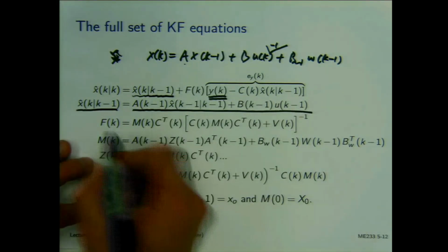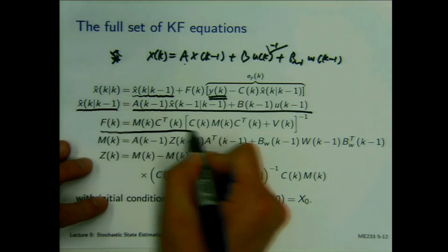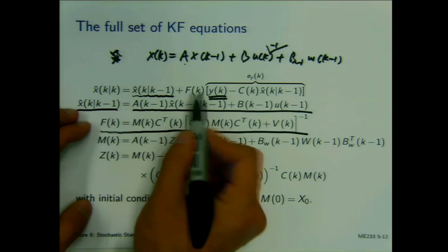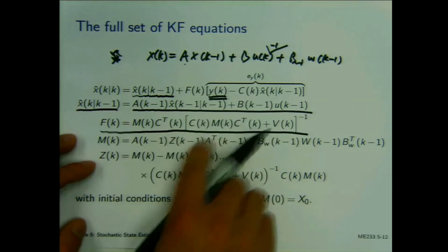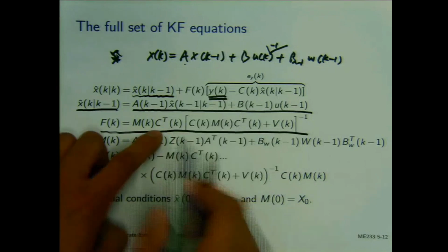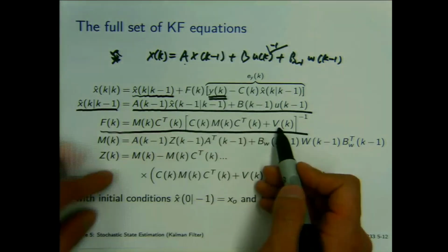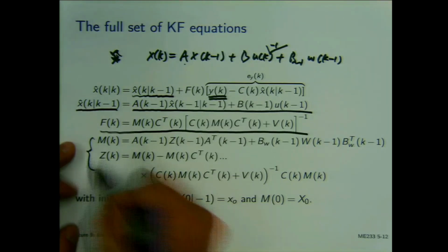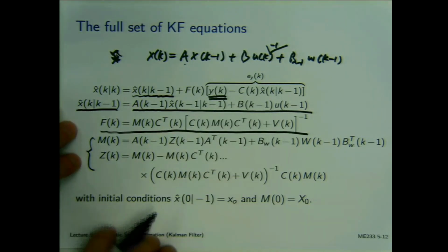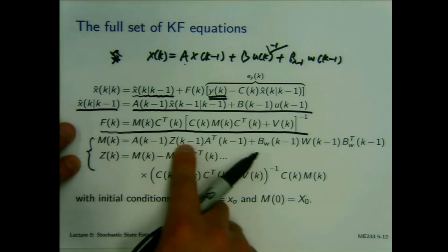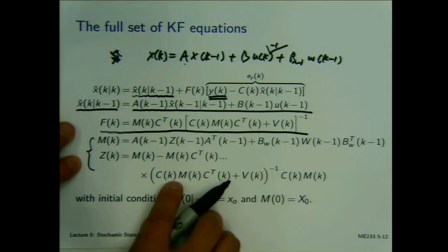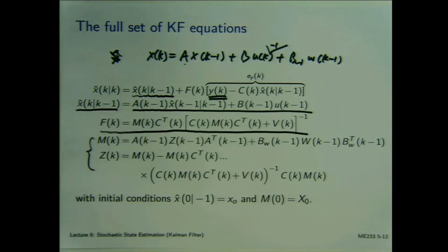And then we have explained that the Kalman filter is an observer. It's optimal in the sense that the update gain is specially computed depending on the properties of the noise terms. And how these M matrices are computed is just what we have discussed in the last 2 slides. M is dependent on Z k minus 1, but Z k minus 1 has some kind of regression term. And that's how a full set of Kalman filter equations looks like.